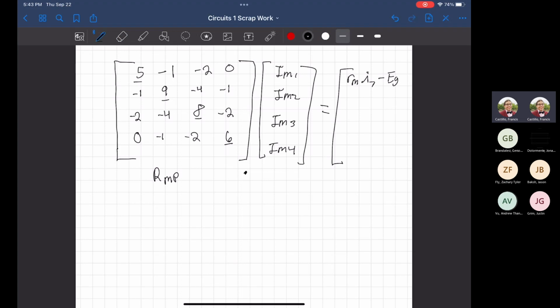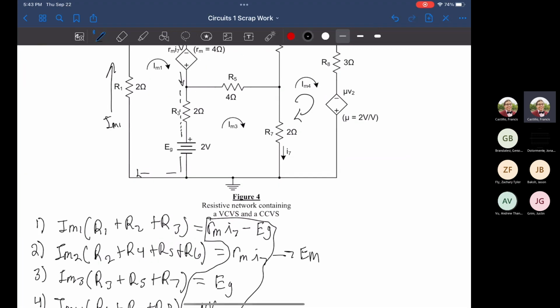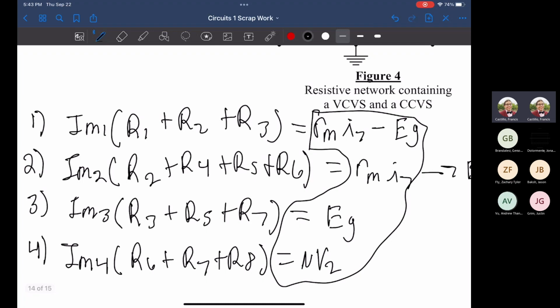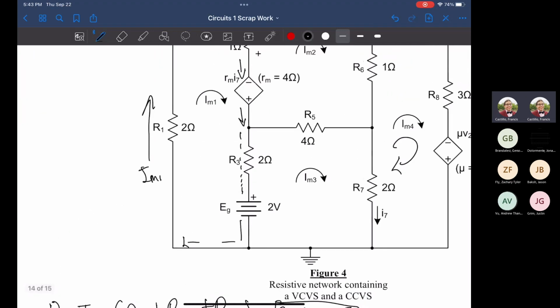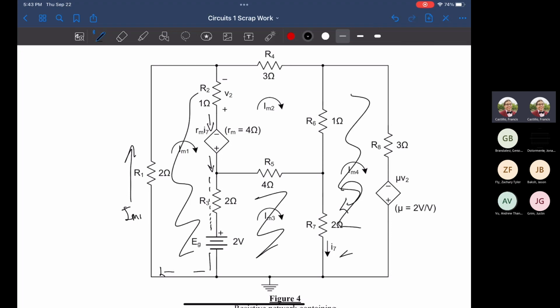Minus E. This is just negative since it went against our voltage. Oh, what's the negative? Let me write it in. The reason why I'm putting in a negative for mesh 2 is because we already wrote it down for mesh 1. Not even that. We're only going to be looking at mesh 2. Ignore everything else. We're saying the current is traveling in a clockwise orientation, so it's traveling around here, here, and here.